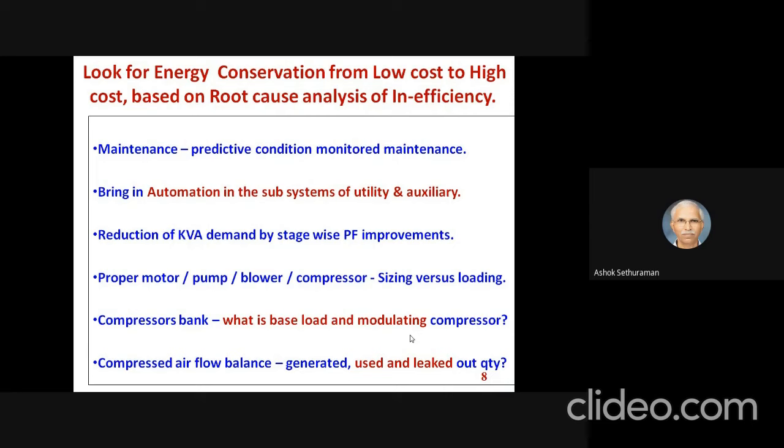Many of the industries, most of the industries, they do it only in the power house. Whatever you talk about the load and compensation, it is not done in many of the industries. In fact, recently we did it with a big reputed group, having a 4000 kVA capacity. They started revisiting their electrical distribution, and they have done that load compensation, and they're able to almost switch off their active harmonic filter because of this.